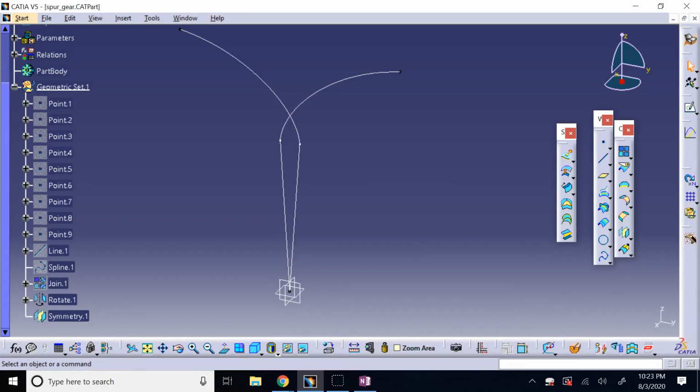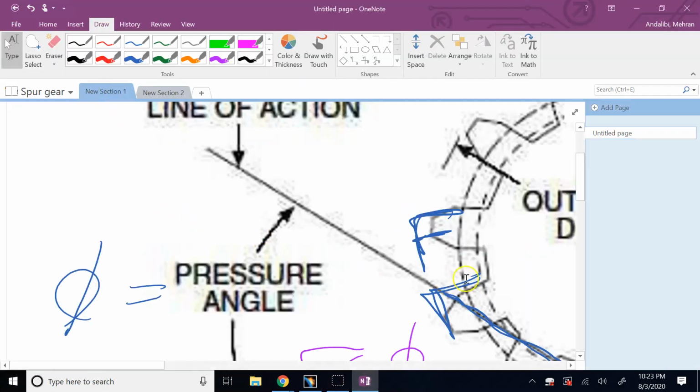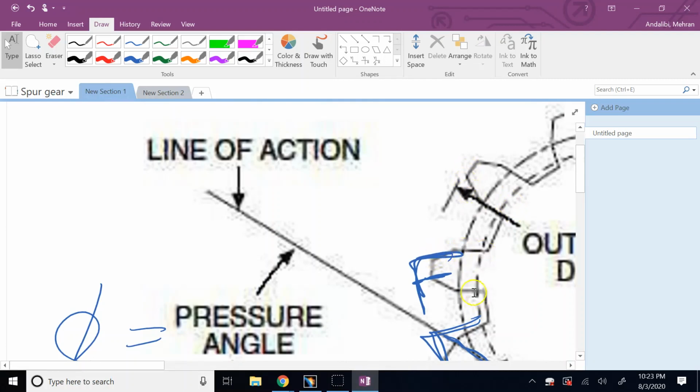Now I'm on page 13. And now these are the left and the right involutes, right? So these are basically this side of the involute and the other side of the involute. So now what I need to do is to cut them at some point, connect them together using a straight line, and then the bottom of these teeth I need to use a fillet. Actually that's a fillet, so nothing special. Sometimes there is an undercut, but here we don't do undercuts, so we just keep it as is.